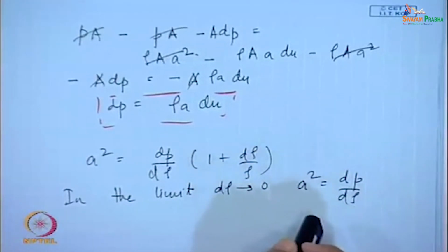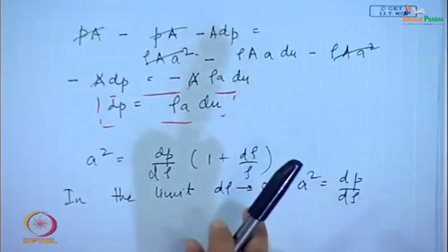You are already probably familiar with this expression, although I do not know whether you had known the derivation earlier or not. Now, remember one thing: this process firstly was adiabatic and reversible. Why? First, the frictional effects were confined to the inside of the pressure wave itself. Since frictional effects are confined to the inside, there were no velocity gradients on either side of the wave, and we can assume the process to be reversible. In addition, there were no temperature gradients except inside the wave. So, we can assume that the process was adiabatic as well.